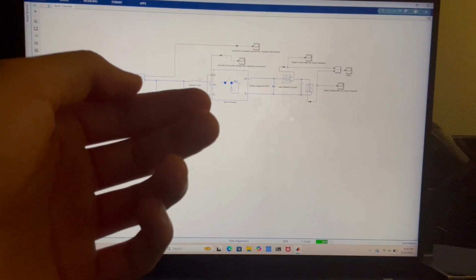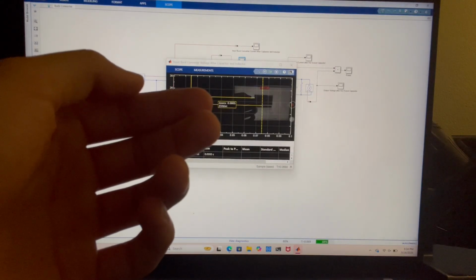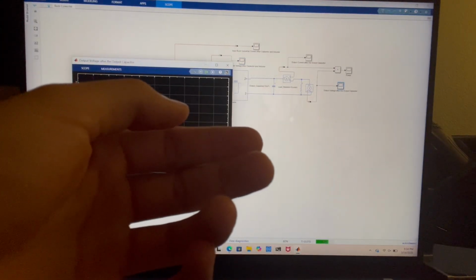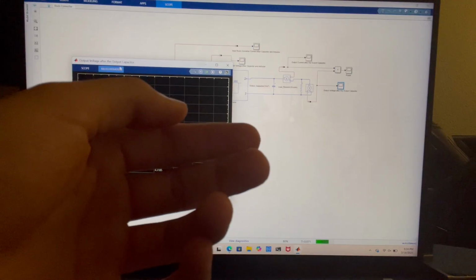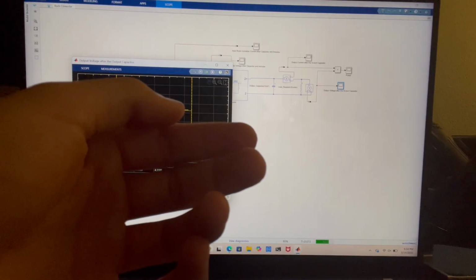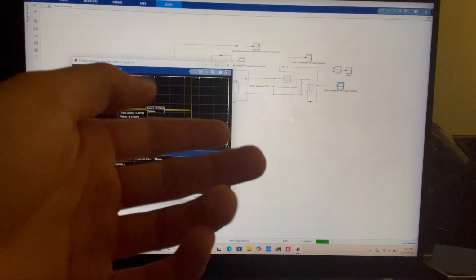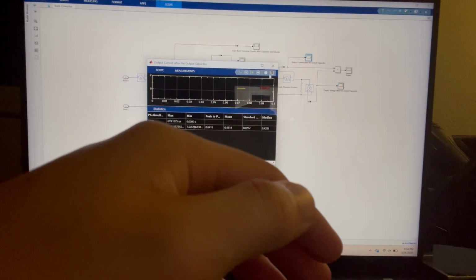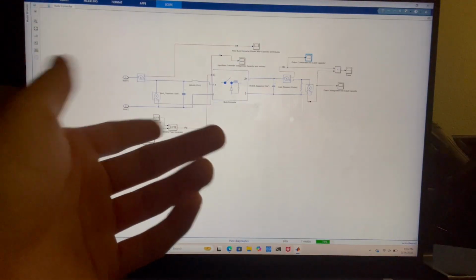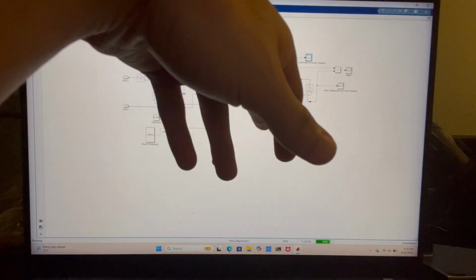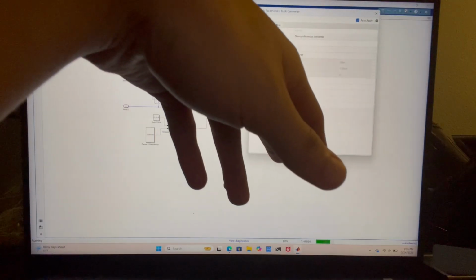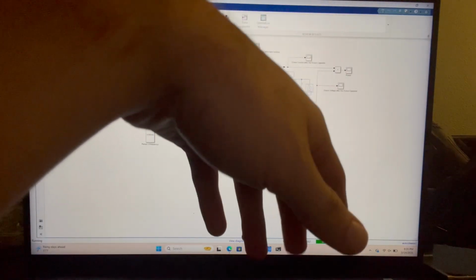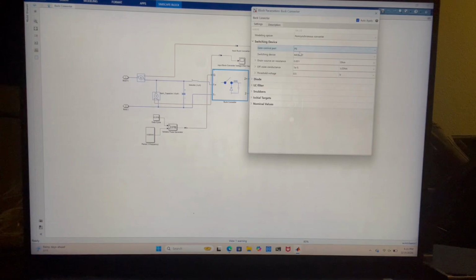Still our 30 kilohertz. Oh, that's our actual input voltage. And what's our output? Should be, yeah, should be 4 or 5 volts. 4.3. And we have a current of about 600 milliamps. So we can just adjust this a little, not the load resistor, just the internal. Let me stop this. Sorry if my hand's in the way. So doing the math, I need to mop up my paper.